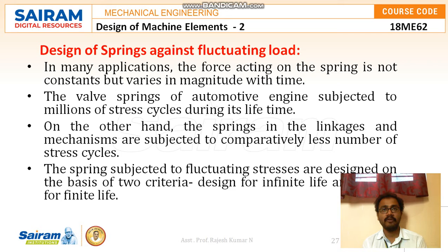Usually the storing of mechanical energy will be there. But if you see the springs used in the linkages, the mechanism loading is comparatively very low, and the stress cycles that result are also very few. Both the springs are located on the engine only, like an automotive engine: the valve spring and also the linkage springs. Just now we discussed that the valve spring will have more stresses compared to the linkages. So there will be a fluctuation in the stresses.